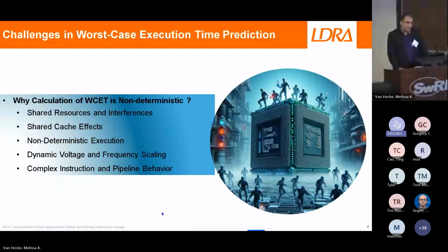In a single core application, timing analysis was easier. You are basically executing, and it really depends on the clock ticks per second it takes for you to execute a task. So it was easy, not really challenging, and it wasn't really mentioned back in the time. When it comes to multi-cores, because we have different resources that are shared across the cores, we're going to have a timing of applications, but it may not always be exactly the same. So it becomes non-deterministic. We can't exactly predict how long it will take to execute specific tasks or programs.